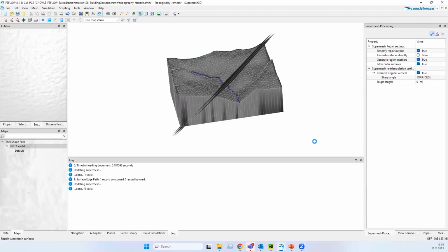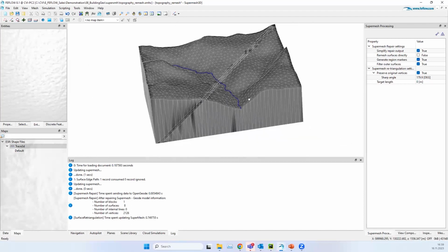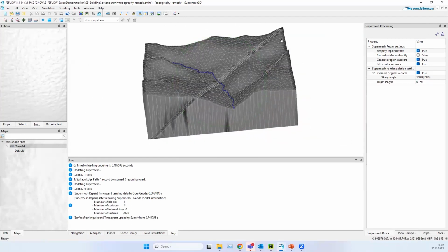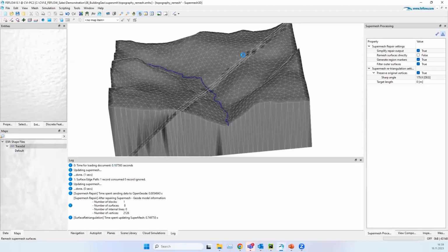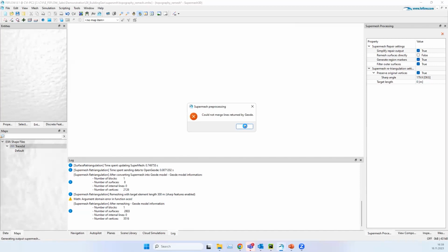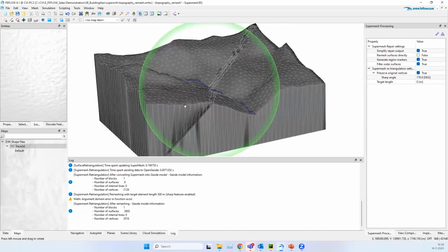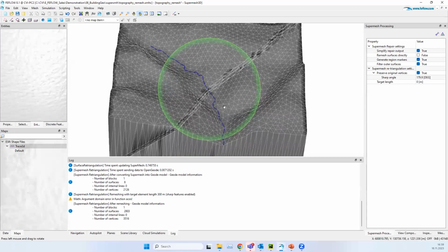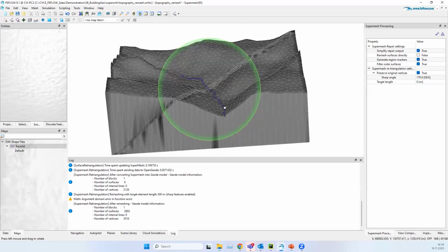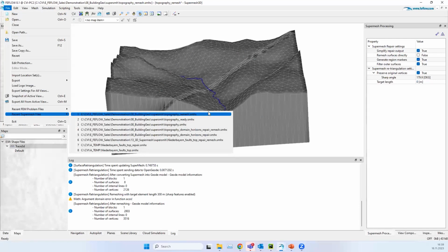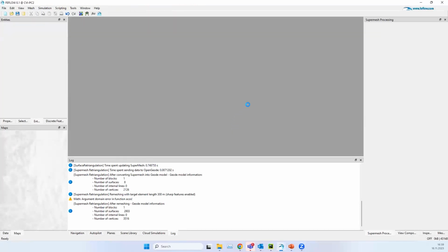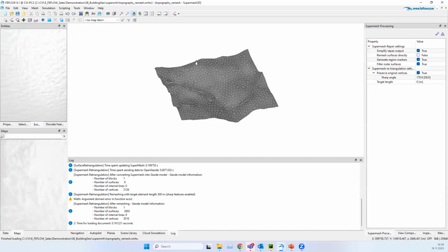And then if we call the repair tool, this requires a couple of seconds normally, and this gives you the outcome where the surface is thrown out of the part that is not needed, and then if you call a remesh, you can improve the quality.